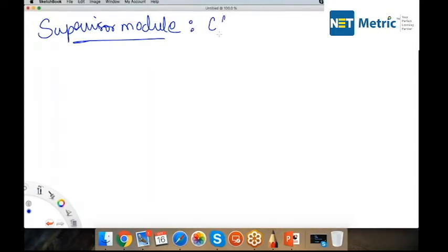Because there is no mid plane, there is easy airflow between the front and the rear ends of the device. Therefore, the cooling efficiency is much higher. Before, there was a mid plane which was like the connection for modules that were getting inserted from the front and the rear ends of the device.